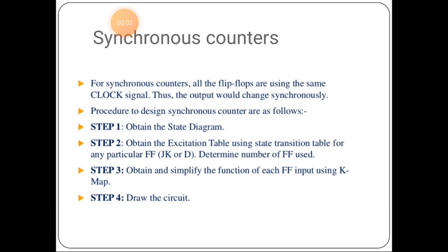Today we are going to discuss synchronous counters. The main difference between a synchronous counter and an asynchronous counter is that in an asynchronous counter, only the first flip flop is triggered or clocked by an external clock signal or count pulses, and all other flip flops are triggered by the output of the other flip flops.